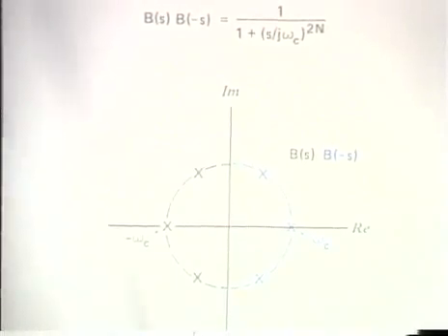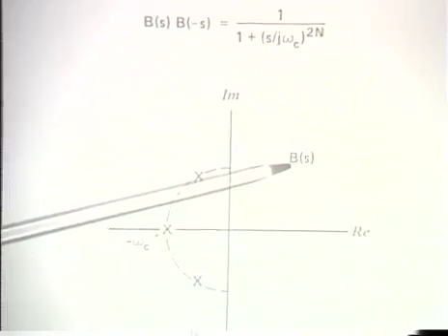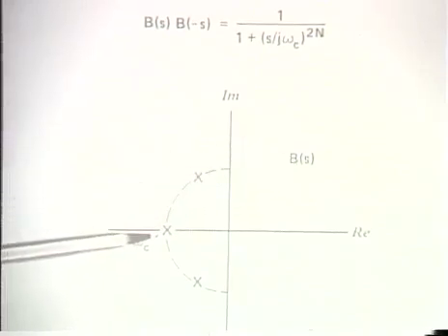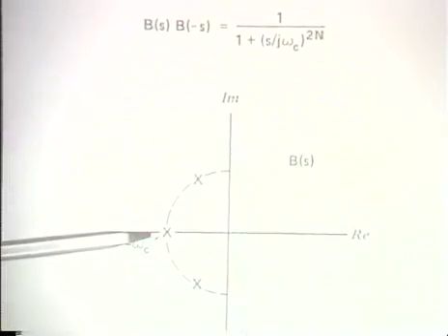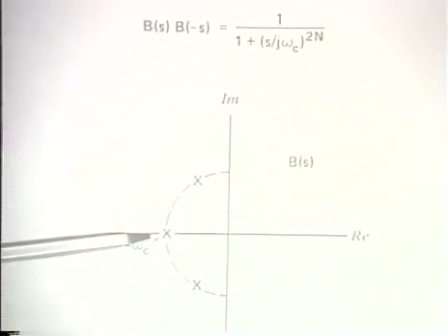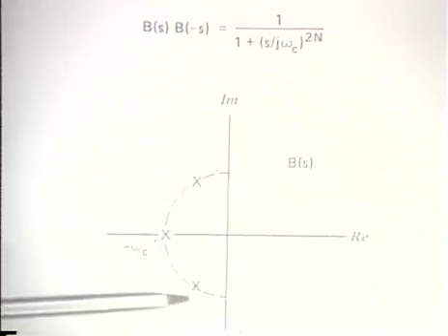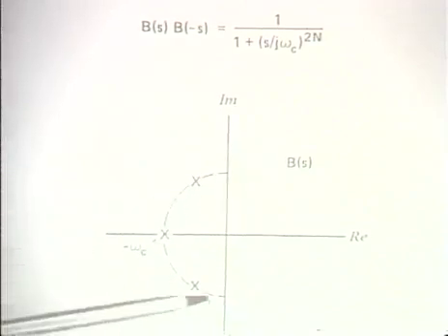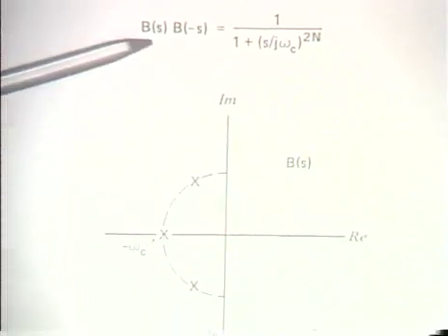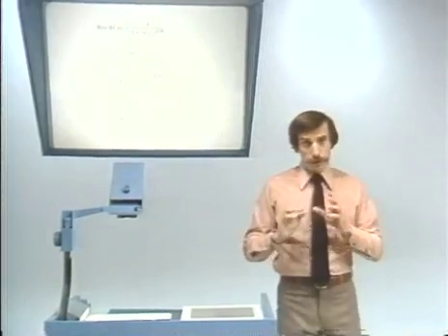And so the transfer function for the Butterworth filter, for this particular case where this designates the parameter omega sub c and capital N is 3, namely a third order Butterworth filter, is this set of pole locations. Given those, of course, we can figure out simply through algebraic means what the transfer function B of s is. All right, so that's what Butterworth filters are.